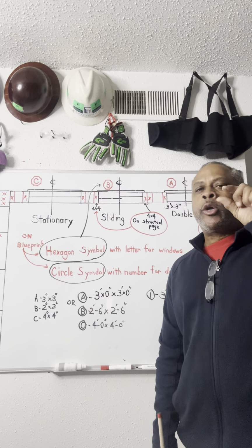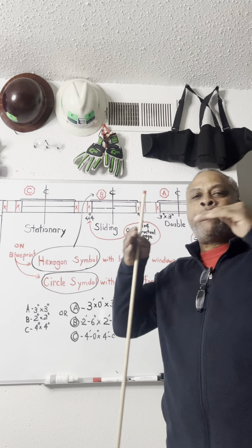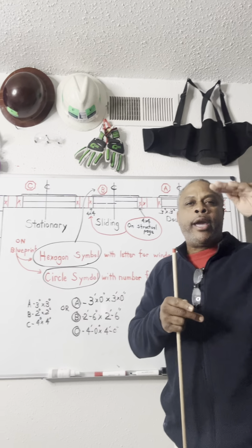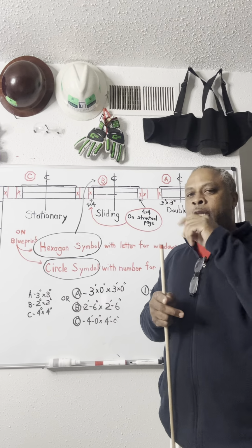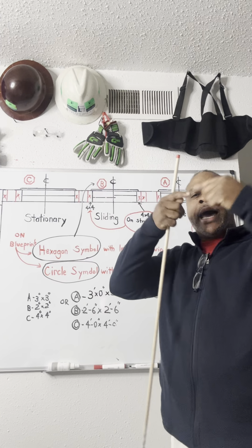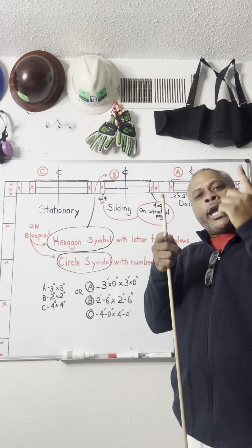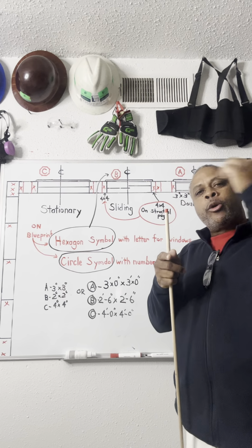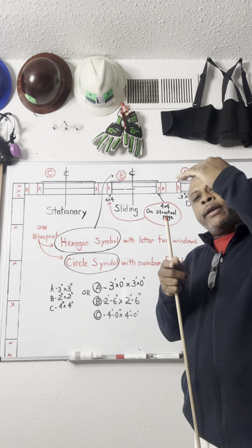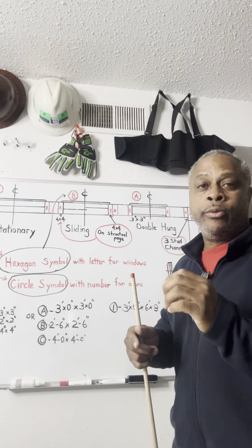Your jamb is 3/4 of an inch. You can always put plywood at the top between your header and your jamb and nail that together with your finish nail. Or you can put shims from each side until that jamb is level, and then nail your jamb and your shims together. Or you can nail your plywood spacer up underneath, in between your jamb and your header. You can always do that.